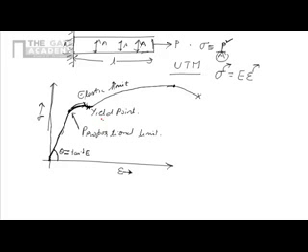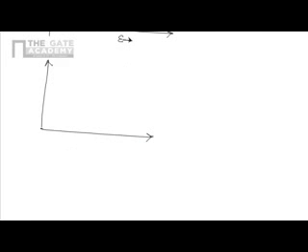So for all practical considerations, I can just draw the diagram again. It will look like this. It is a straight line. Then this is the point at which proportional, elastic, and yield will be very close to each other. They will be almost at the same point. Beyond yield, the curve doesn't remain linear. It becomes some arbitrary curve. Obviously, this is sigma and epsilon.